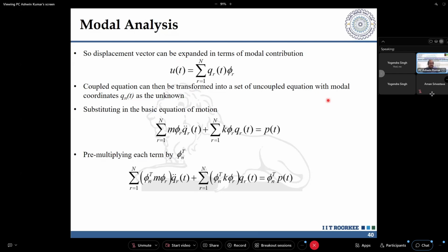One thing that we left out is how you solve this if you look at Midas in the evening. You will be looking at response spectrum analysis. Maybe you will have time history analysis shown, and which button you need to check to do a time history analysis. You already know response spectrum analysis. The modal combination method will come into the picture.